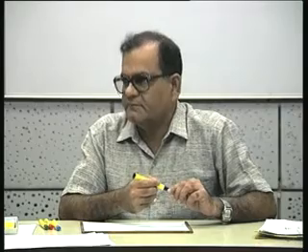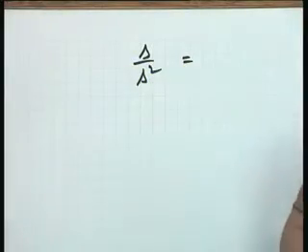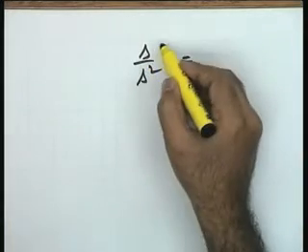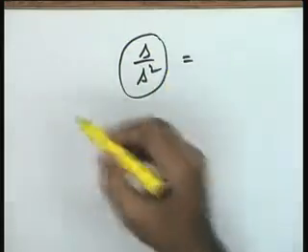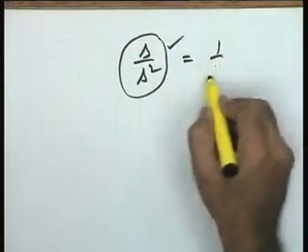Yes, please. What would be the type number of a system, say s by s squared? S by s squared is a type 1 system obviously. But that means you are cancelling the pole and 0. Surely. But you said that in practical cases you can never. You see, when you say s by s squared, it means you are giving me a model. So, it means this is 1 by s.